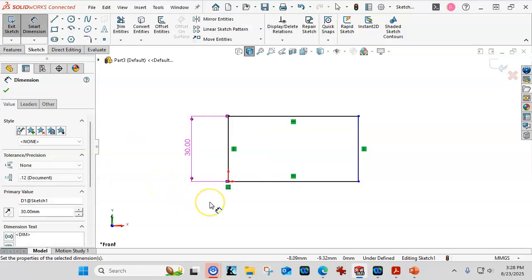All right, my recommendation is that you go for objects over points, but if you're used to AutoCAD, Inventor, Fusion, a lot of times they go point to point, and it's okay to go point to point. Just realize that there are certain instances where point to point will allow geometry to orbit.